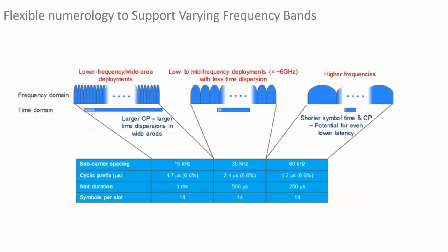So that is what I was talking about earlier. So here you can say we have frequencies up to, you can say, less than 1 gigahertz. Here you can say frequency less than 7 gigahertz. This 6 is wrong. It should be 7. So earlier it was 6 gigahertz in case of 5G, but now they have increased FR1 to up to 7 gigahertz. And then we have higher frequencies. It can be between 24.2 gigahertz